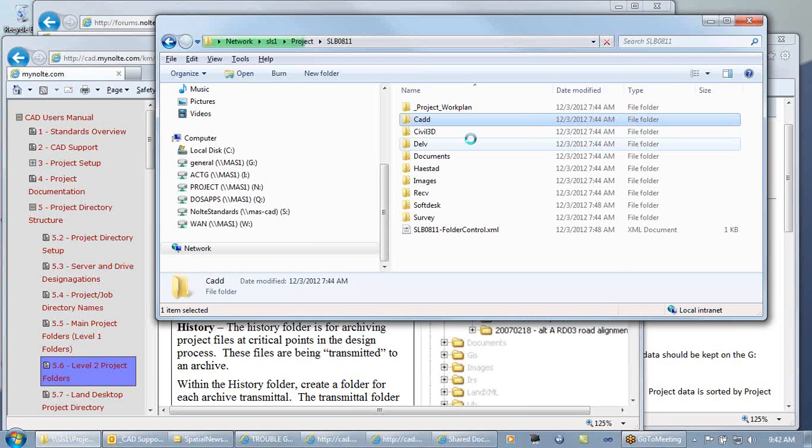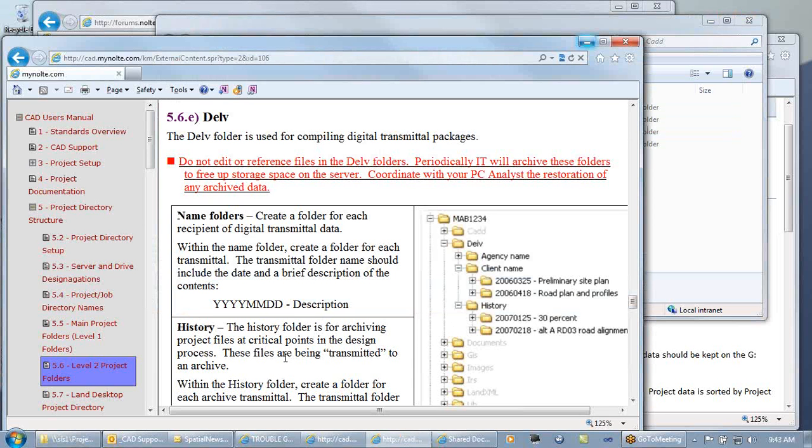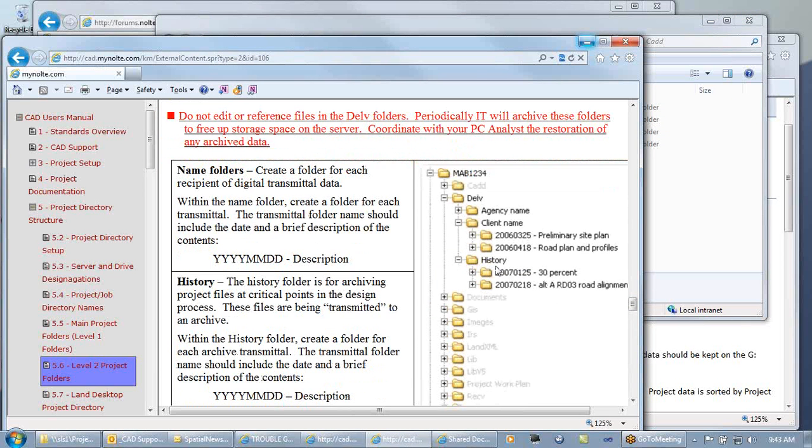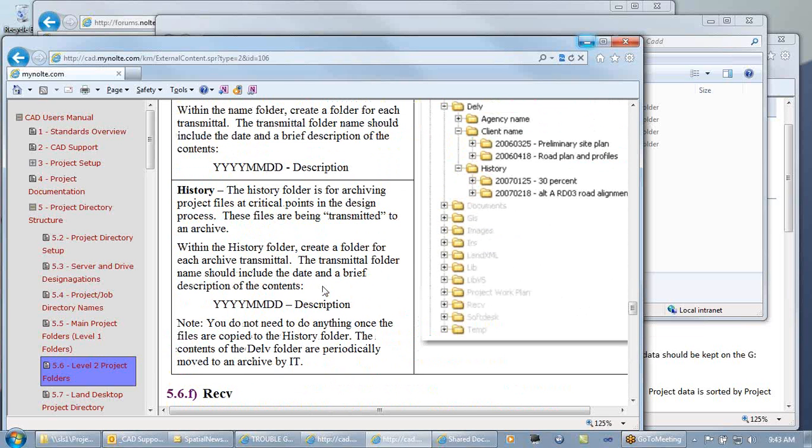So when I get in there and I see four proposed topo drawings or map, site plans, I don't have to guess which one to use. There should only be one of every file here, and that makes it real easy to know which one I XREF, which one I work in, which one I'm going to find that line type in, or that line in, that I need to modify. So you only have a single copy. If you do need to back stuff up because you know it's going to change or you want to capture something, do it to the deliverable folder here. That way if you need to revert, you can copy it from here, overwrite the one back in the master folder, and all your X references should work just fine.